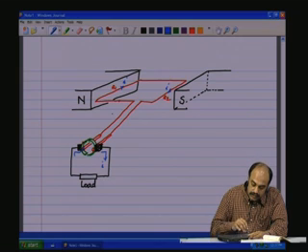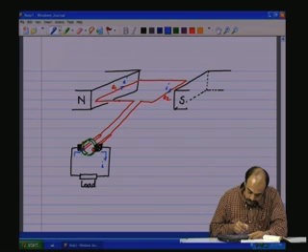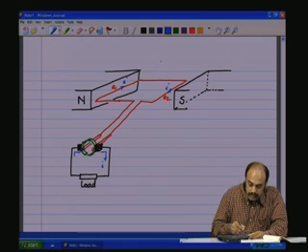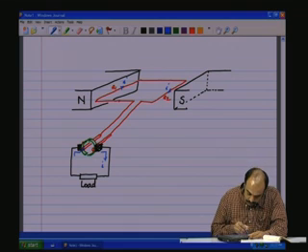Now as the coil is rotating and comes into an orthogonal plane, it becomes 0, the voltage becomes 0 and starts going negative. So when this has turned 90 degrees, these two splits are going to be at around the center of the brush, and then on further rotation,